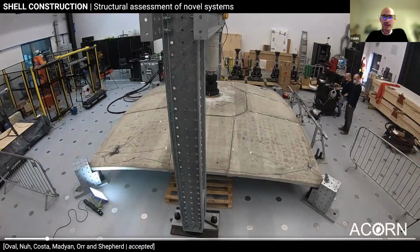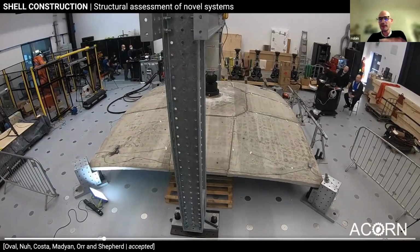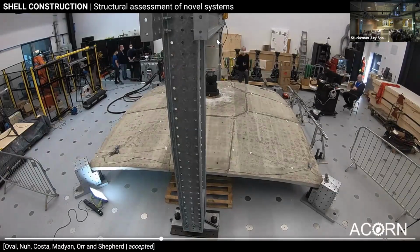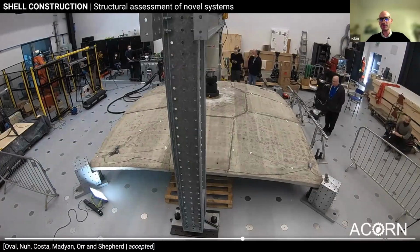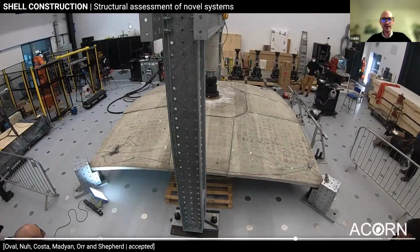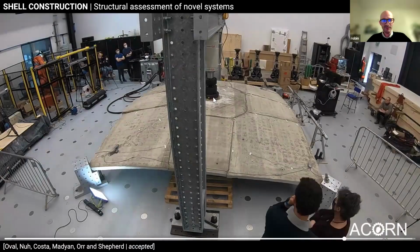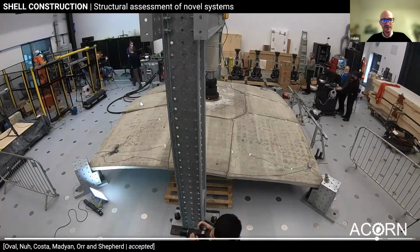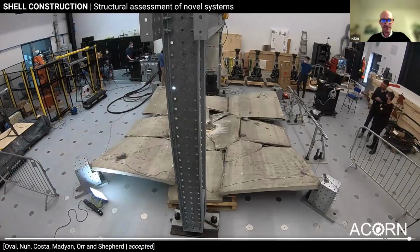Then we brought it back down to be able to assess how the structure behaves by loading it here in the middle to see how it behaves, because it's not just a concrete shell, it's made of these module segments with dry joints, so it's closer to masonry behavior. So I wanted to know how it was going to fail, and you can see that this is starting to go up while this was pushing in, and then you have this asymmetrical behavior, and then a quite sudden collapse,